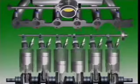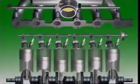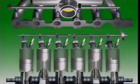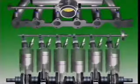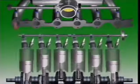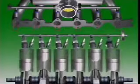Group 1 injects, then 360 degrees or 1 crankshaft rotation later, so does Group 2. This happens regardless of the position of the intake valve. Just 1 injection provides the full quantity of fuel for each cylinder during that engine cycle. In some applications, different modes of injection are combined so that the mode changes according to the operating conditions.